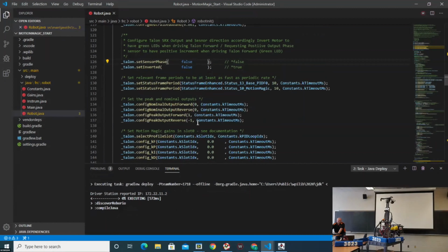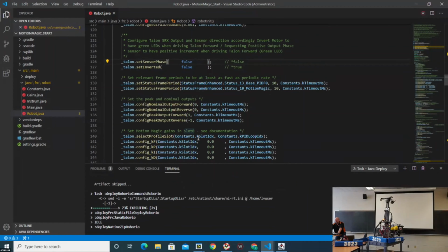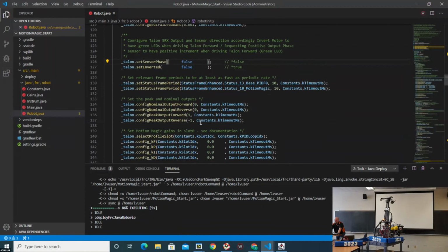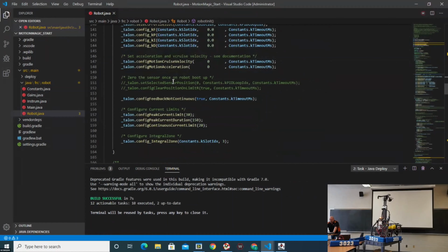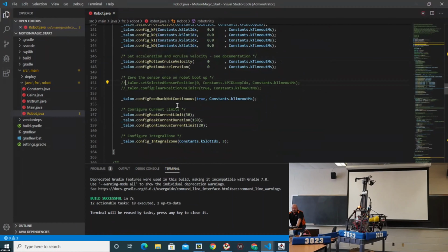You can see in the picture-in-picture that the robot is halfway up, which means if we had left this line here uncommented, this would now be our new 0 position. And since we're using an analog feedback device, we'll know exactly where this robot is, even on a power up.